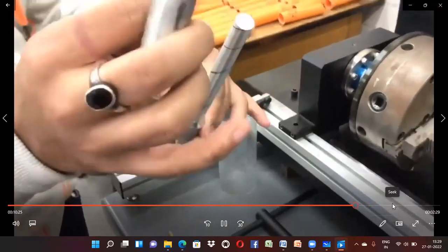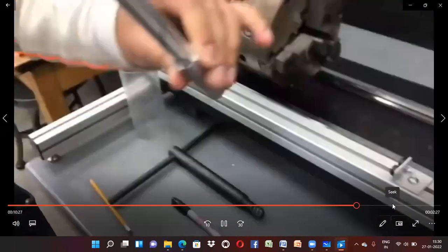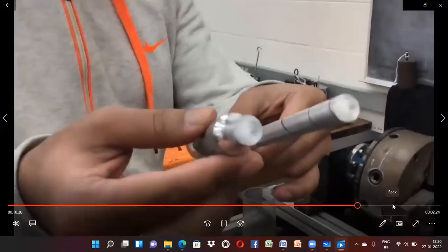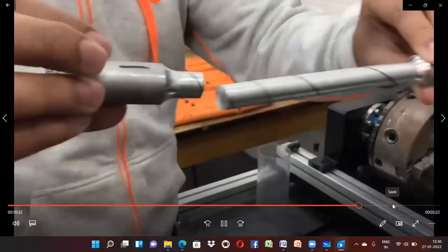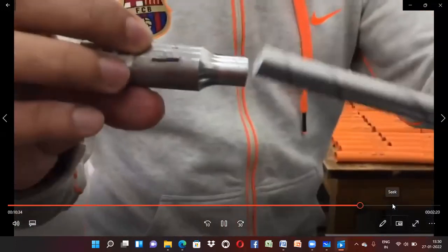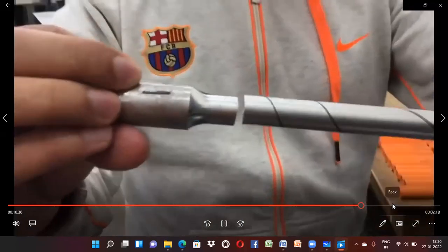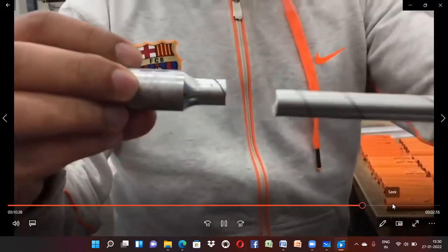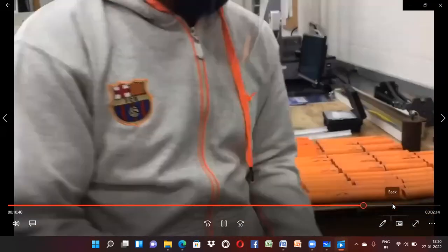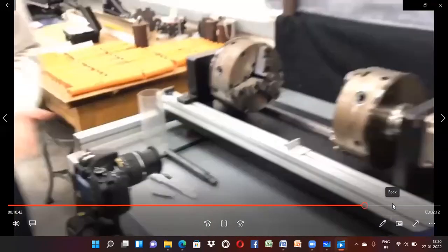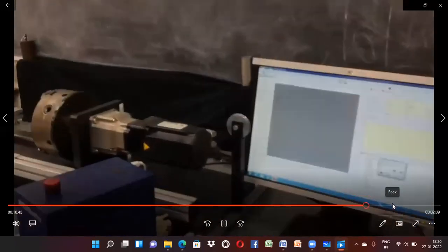This is very interesting. If you recall the tension experiment, or at least the video of the tension experiment, the fracture surface, still hot. Yep, still hot. The fracture surface was 45 degrees. In this one, the fracture surface is totally normal to the axis of the specimen, right? So it's a perpendicular normal. And it fractured on that surface for some reason. Again, you'll learn more about that later this semester in 303 or 306.